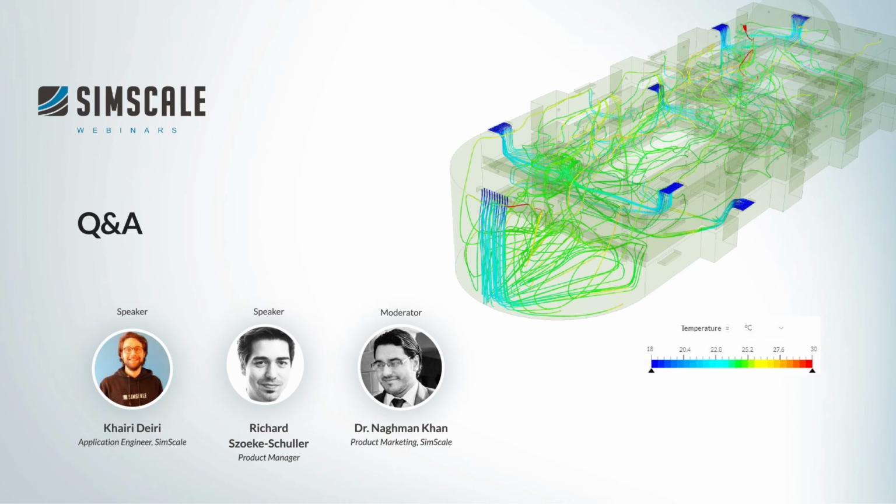or even tunnels, where basically the idea is that we simulate the air domain of, let's say, that car park, and we assume the smoke is basically a contaminant that is being driven by the air. So we track that by what's called a passive scalar. So we assume that the smoke or the CO2 has similar density to the air. And then with that, we track how its concentration is distributed inside.